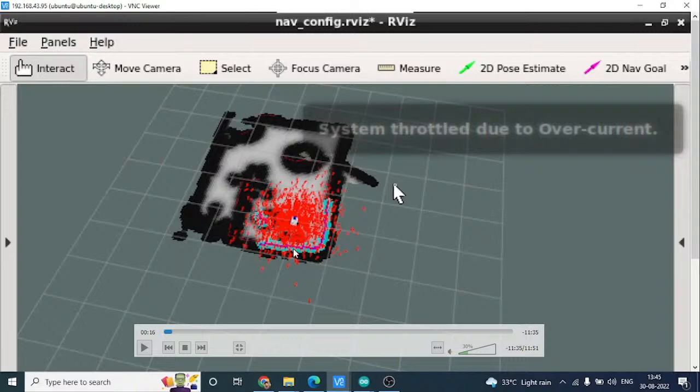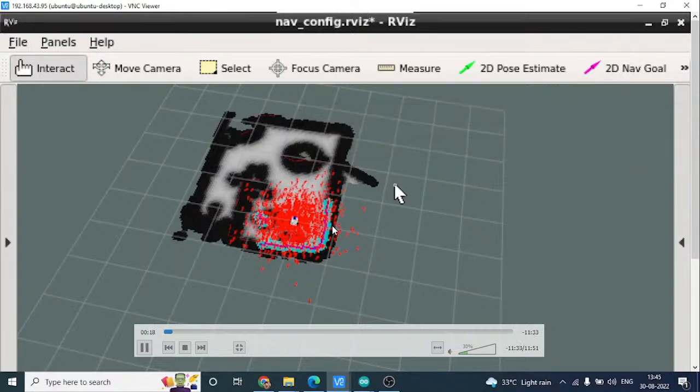And this is a room actually. This is the walls of the room, and there is a round object here. This is a solid object, and there is a table here. So the robot is only allowed to go in these white spaces. All these black spaces are walls, obstacles and solid objects. So it can only travel in these white spaces. Then this is the local cost map, and this is the global cost map.